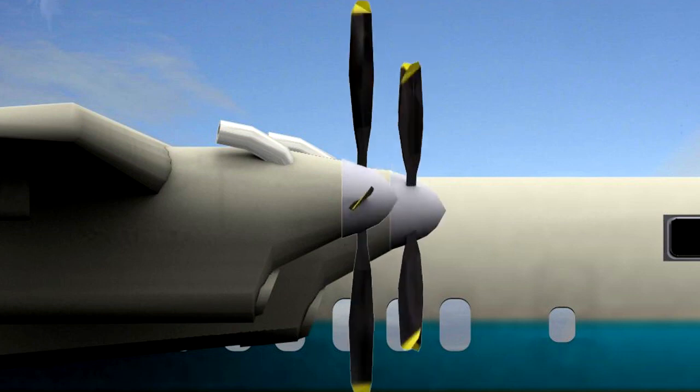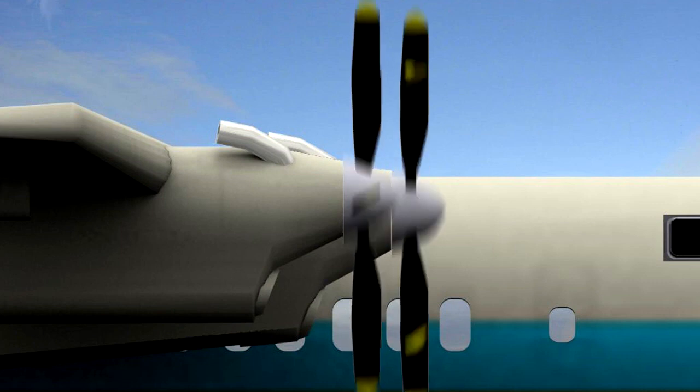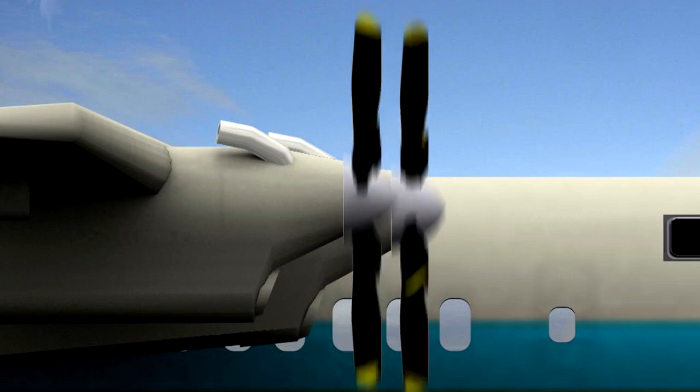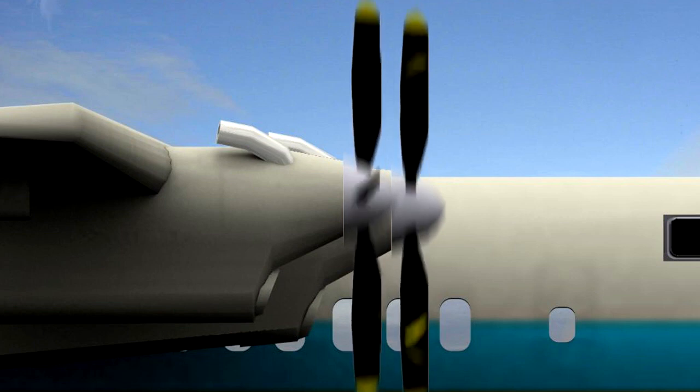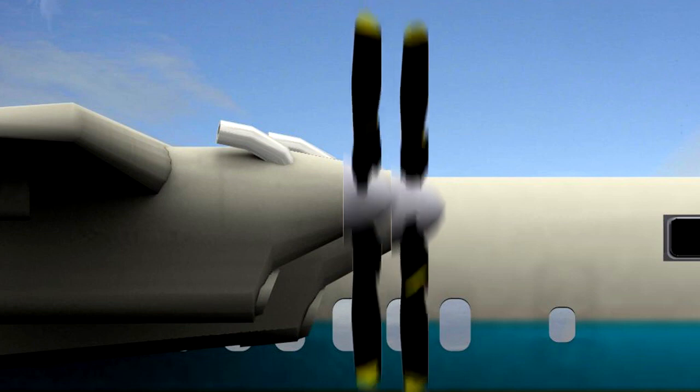In order for the propeller blade to direct air forwards and create a rearward acting force, the blade angle must change to the position illustrated here. The blade angle required for the propeller to generate reverse thrust is known as reverse pitch. Because only a change of blade angle is required, a propeller aeroplane can switch from forward to reverse thrust far quicker than a jet aeroplane.